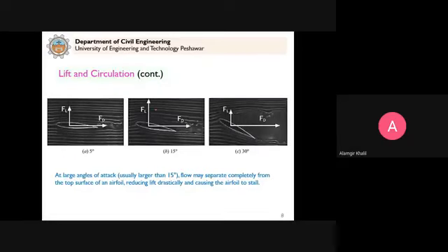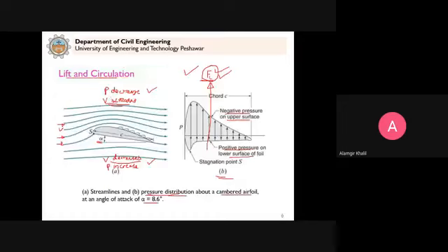Now, before I said that in these lift forces, the angle of attack is a very important parameter. This is the angle that the chord C makes with the horizontal, and it is very important, clear, because it directly affects the lift force.